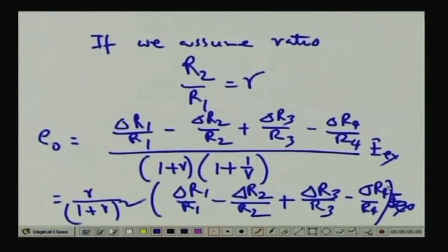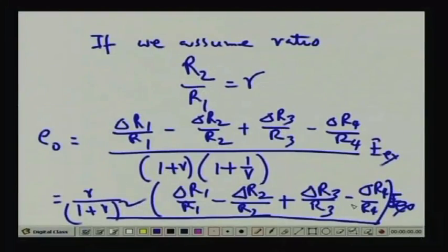These expressions we have shown first in the basics. These equations will be utilized for all unbalanced Wheatstone bridges. So, in both the column type load cell as well as the beam type load cell, we will use this unbalanced Wheatstone bridge equation.